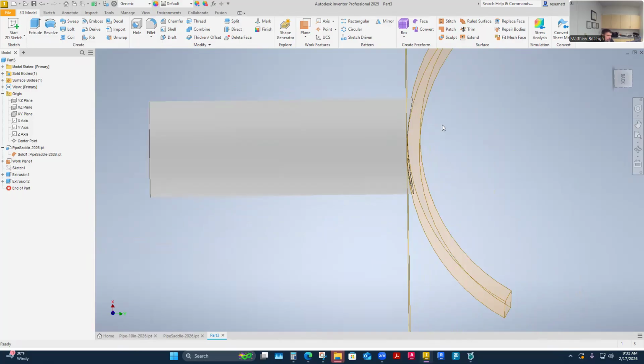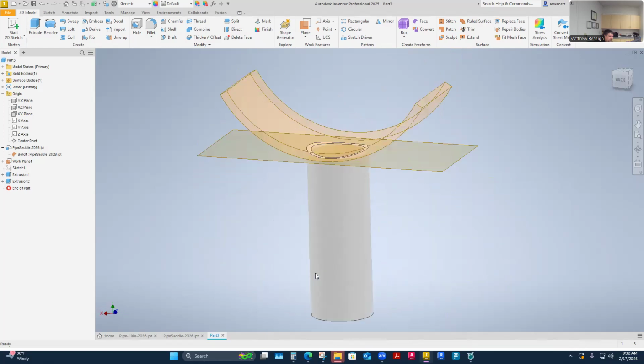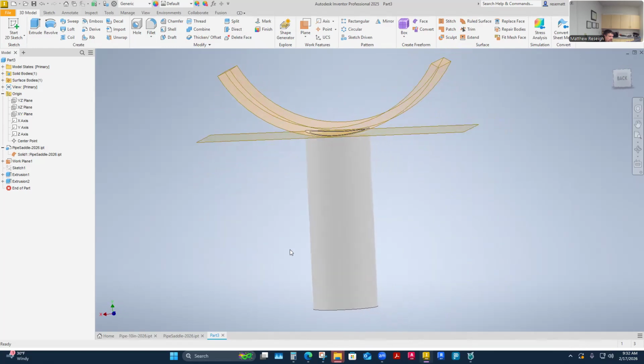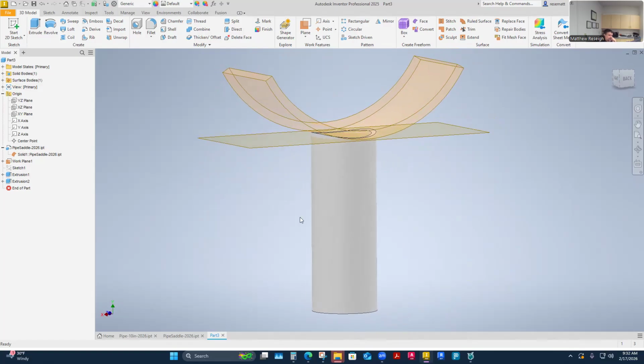The other thing I can do is make a piece of paper, a part that has almost zero thickness, wrap it around this thing and create a cope pattern, and deliver them a one-to-one printed cope pattern. They could wrap it around their pipe, maybe spray paint it or mark it however, and then put that little cope in. So there are a lot of different ways this little part can be made, manually by hand or with expensive machinery if the company has it. But that's all I really need to do there.